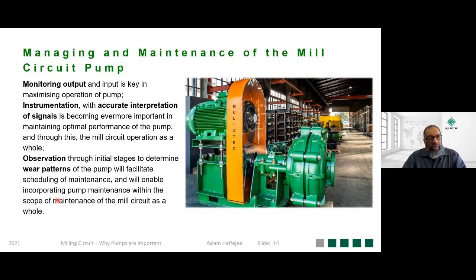One other very important aspect of maintenance is observation. This is what we've just mentioned: monitoring your different parameters, the amps the pump is drawing, any noises coming out of the pump, the pump itself physically, temperature on the bearings, etc. And the important thing will also be to see when your output starts declining. You can monitor this on your cyclones typically, to see what output you're getting, your flow rate, etc. If that starts tapering off, the pump is about to wear.